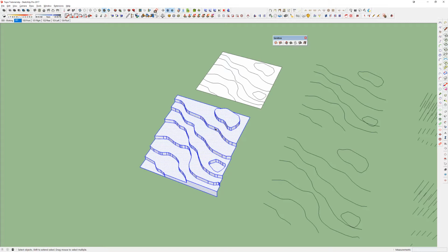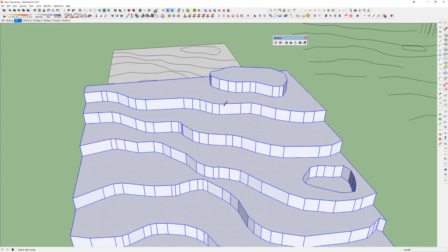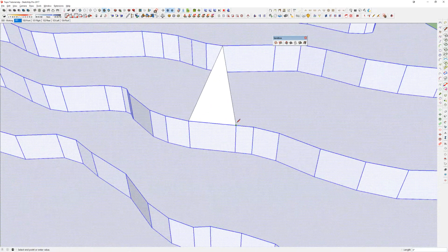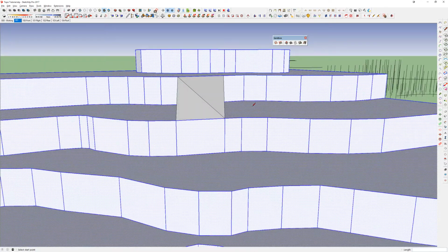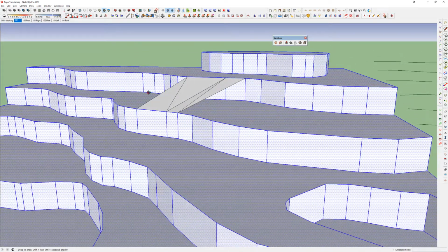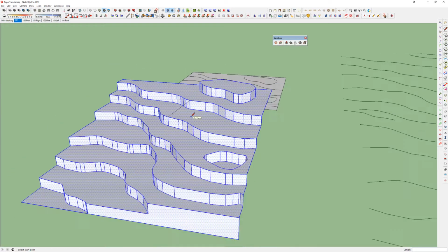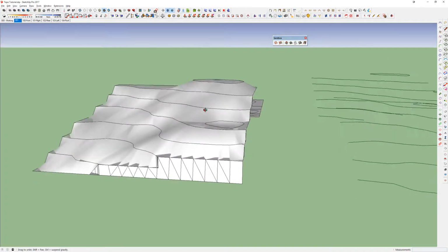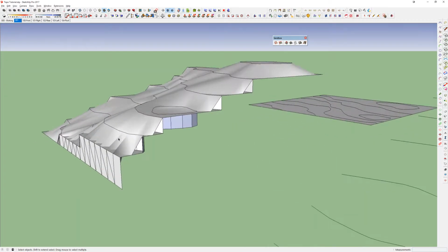So it's going to calculate all these contours, and it's basically going to create what's called a TIN network, TIN, which is just a triangulated irregular network. And for all intents and purposes, all it's going to do is just start creating triangles wherever it can, very much like that, and it's going to fill in these gaps, but it's going to do it more on the fly, and you'll see that in a second. So if I click it, you see that it just created the network.